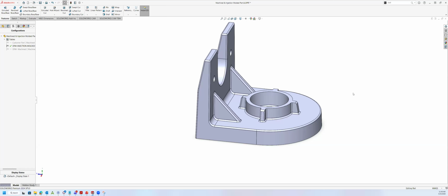On the second side of it, both of these versions would be good to go out of PA12 because it's a solid inside, or more solid inside. And you can use that to your benefit to see how it would function, which we've done in the past with several scenarios to say, hey, how's this going to function when it gets made out of injection molding or when it's machined, if you can do it relatively quickly.